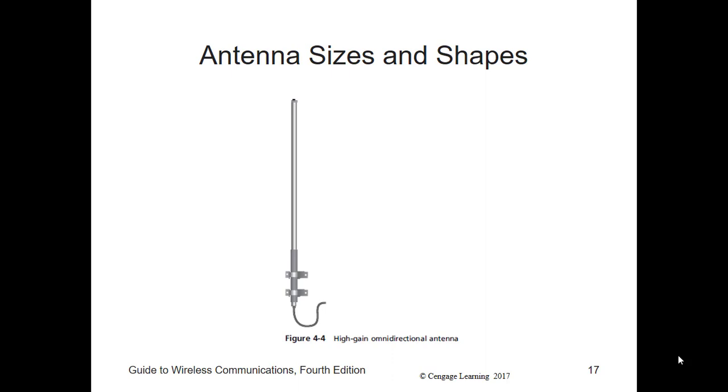These omnidirectional antennas exhibit passive gain because they emit a signal in 2 dimensions only, not in 3, like an isotropic radiator. When viewed from the side, the RF waves from an omnidirectional antenna will propagate from the sides or the length of the antenna, forming a donut-shaped pattern around it and therefore somewhat more focused.